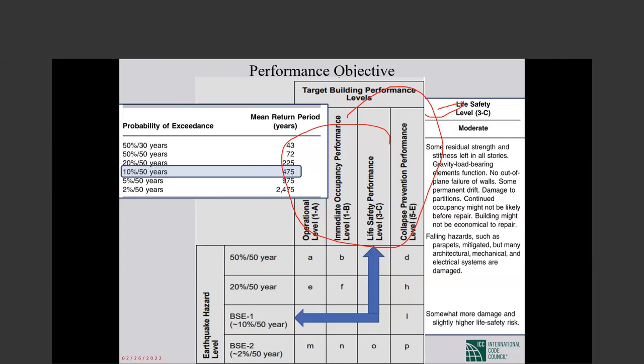In the code for new buildings, in the R value tables, you can see that sometimes a building is a shear wall building. We call it, for example, a load bearing system. Sometimes it is part of, for example, a frame system. And the R value is for the same thing, the shear wall, but the R value in one is more than the other.